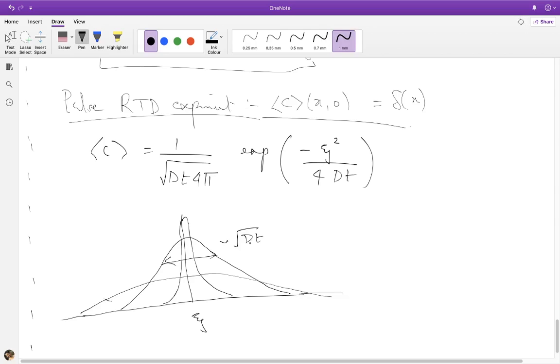Now the key thing is that the rate of spreading, as I said, is determined by the effective dispersion coefficient, D effective, and this D effective is u squared Peclet number by 48. But what is the Peclet number? Remember, this Peclet number is just,